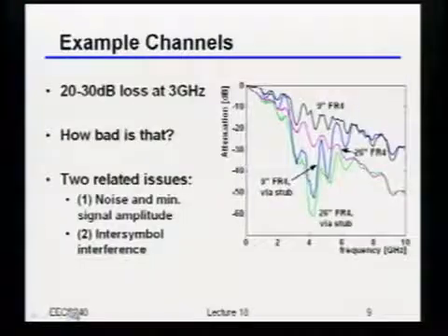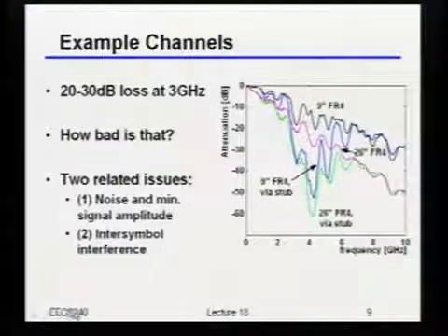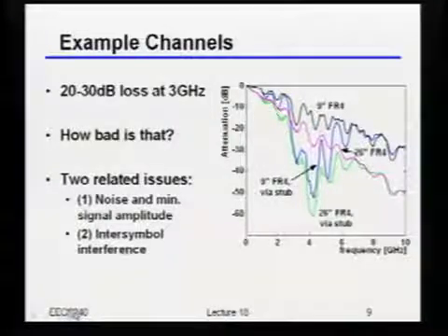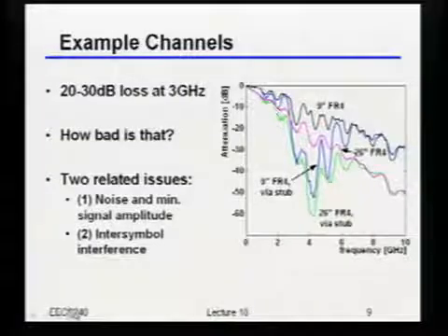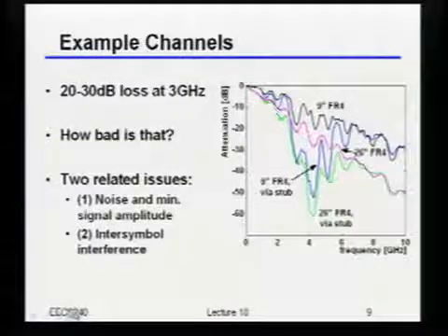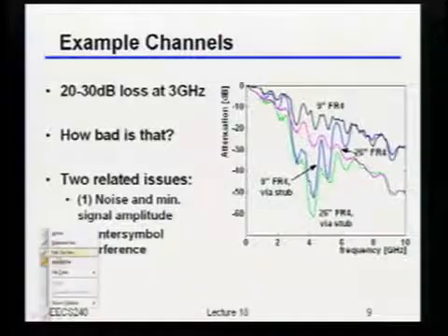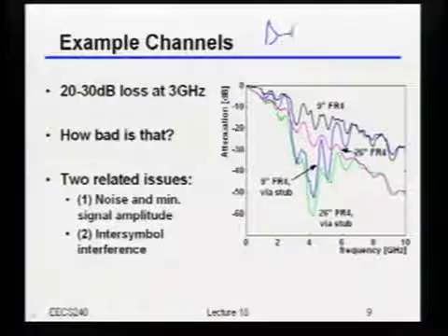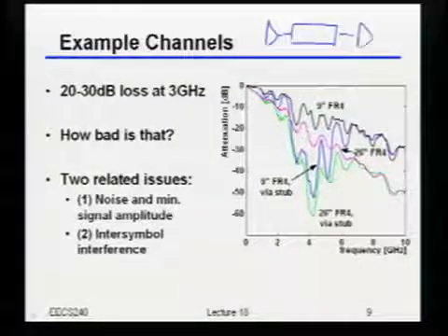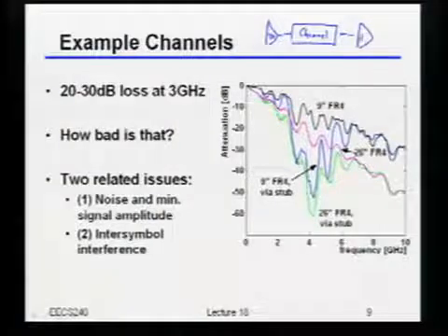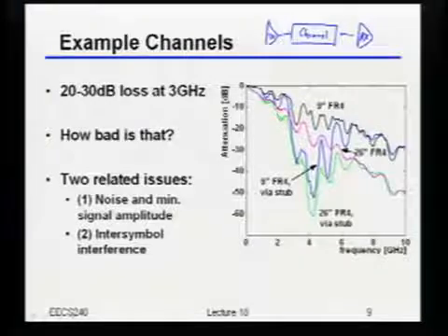So the way we usually like to think about this is to look at just basically what's the transfer function of that. You could say it's a transmission line, but really we call it a channel, okay? And by the way, people call these things channels because they just mean the thing that's physically carrying stuff from the transmitter over to the receiver, okay? So whatever the set of wires and vias, etc. is in between those 2 points, that's usually what we call the channel.